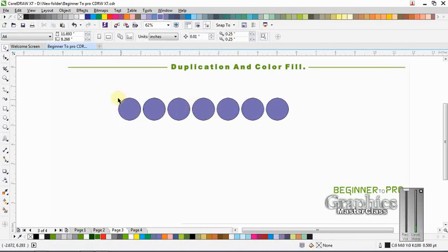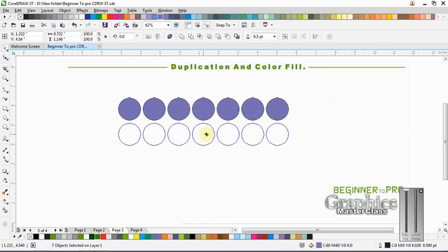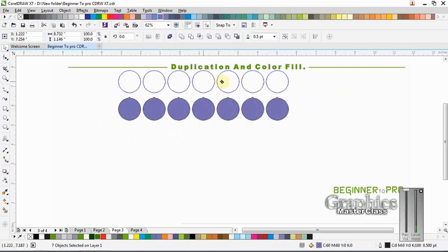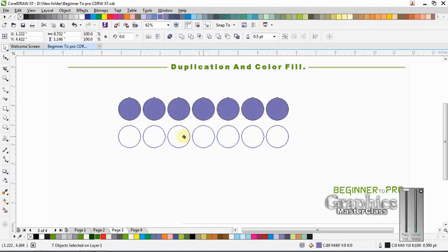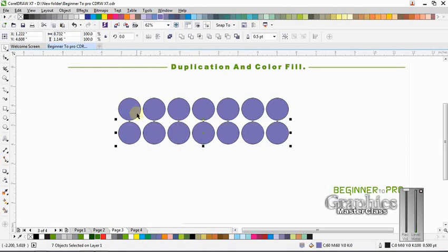Let's select it again. Hold down your Control key and move it. It has been constrained to a particular place. Let's move it down, because this is where I want the offset direction to go. As I've moved it down, now I right click at the same time as I'm holding the left click, and leave it. So it has copied this move that I just did. Once I duplicate, it keeps duplicating in the direction that I just did.